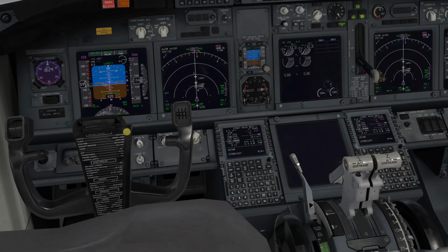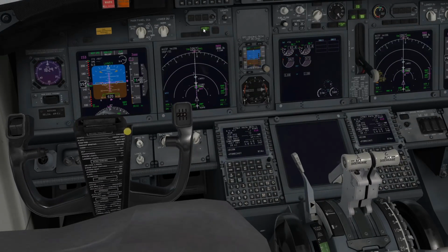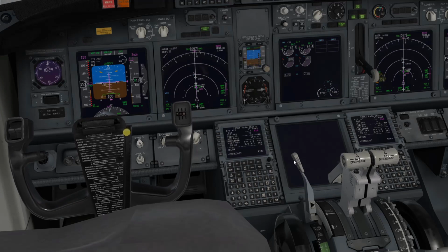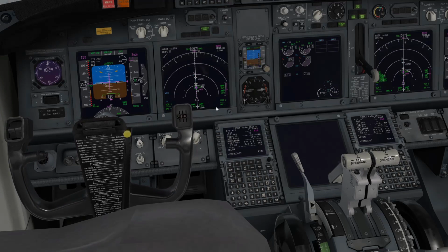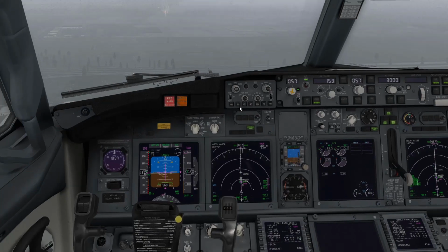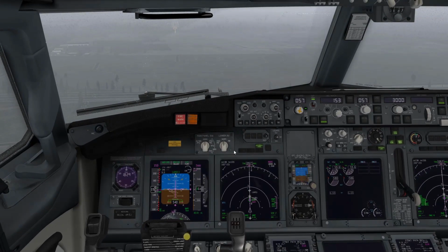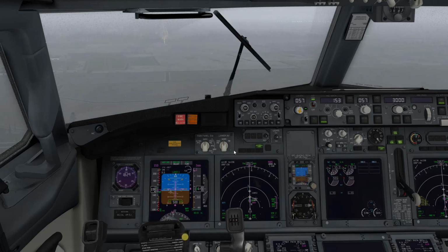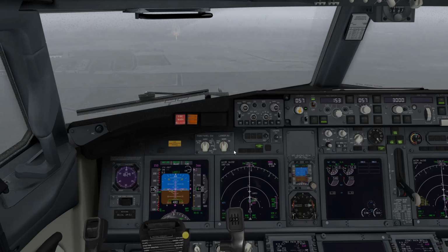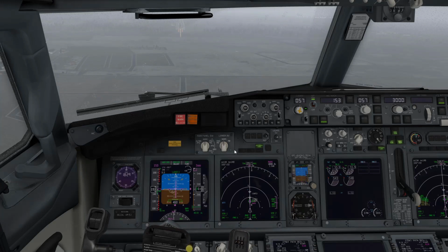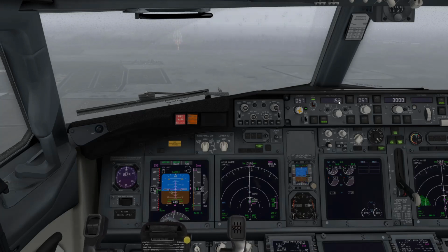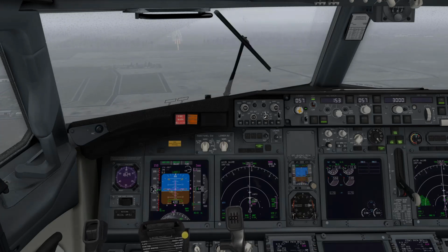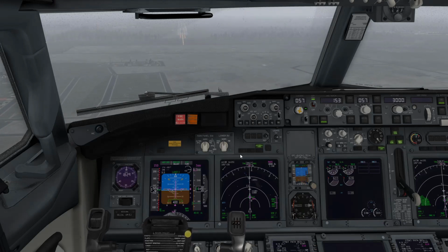We're also going to need to arm the speed brakes. You just lift it up and set it back a little bit. And that is the armed position. There's the runway. Landing checks, landing gear down, speed brakes armed. 500. Flaps 30 set, and command speed is 153. Kind of rushed there at the end, doing too much talking.